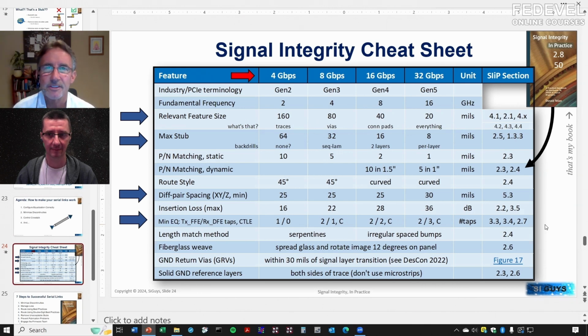And if you're running at Gen 3 or something, there's a good chance your chip can really do Gen 4, so it probably has lots of advanced capabilities beyond Gen 3. Because when the link starts coming up, it'll start at 1, and when that's working, it'll go to 2, 3, 4. It'll just keep going until it's not working anymore. That's just what they call training or bring up or optimization.